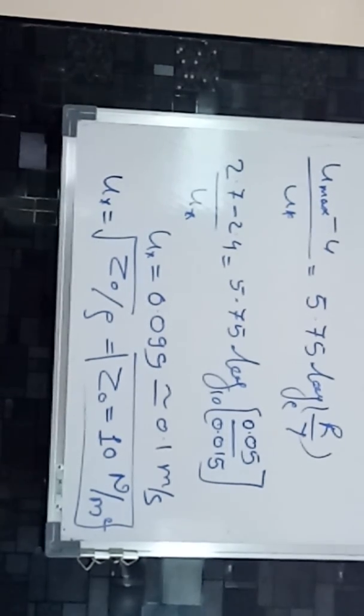So for kinematic viscosity, first you find out U. Take U and kinematic viscosity, which you assume if it is not given. With the help of that formula you are able to find out the coefficient of friction. Then substitute all the values to find one relation, so you will get the velocity and then find the discharge. Okay, next.